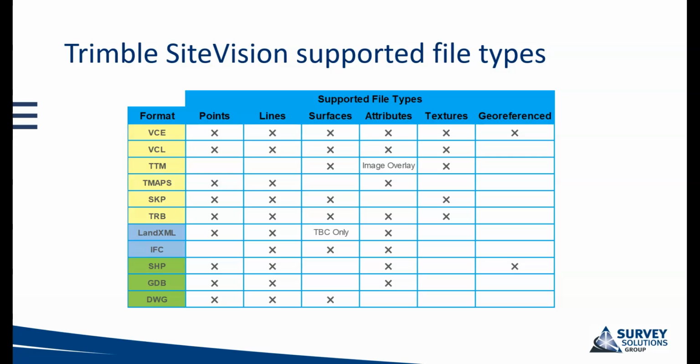In version 4, IFC files actually can contain coordinate system information. However, at this current moment in time, it's not supported by SiteVision, so it will still require a site calibration file. So SiteVision can also use shapefiles.